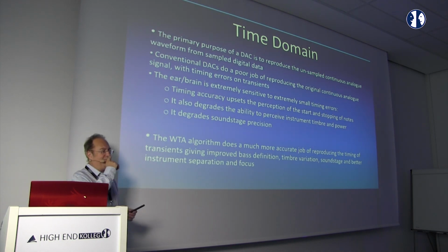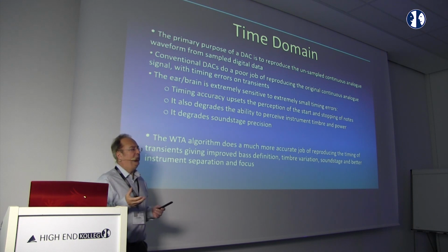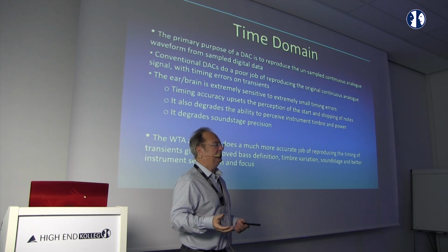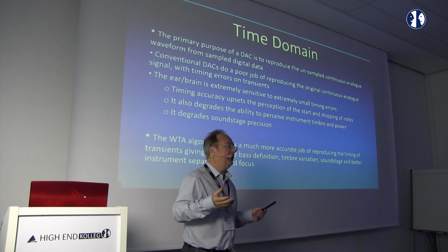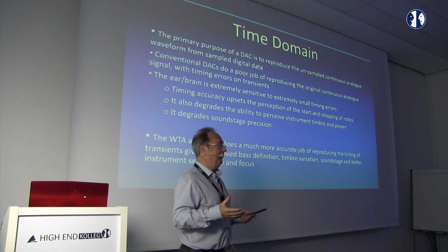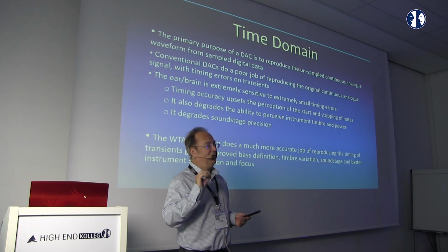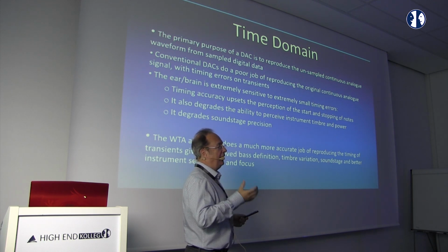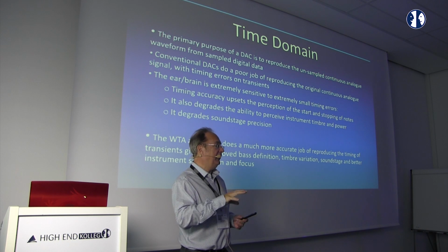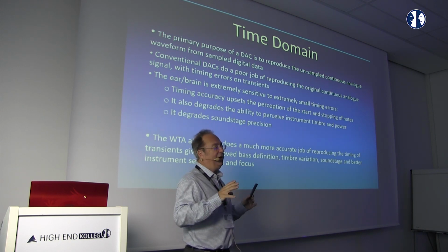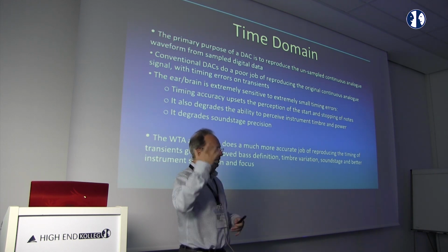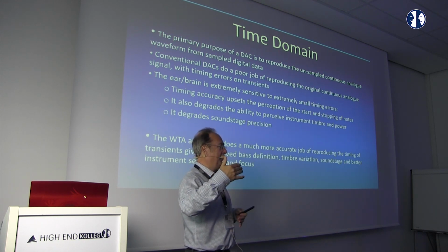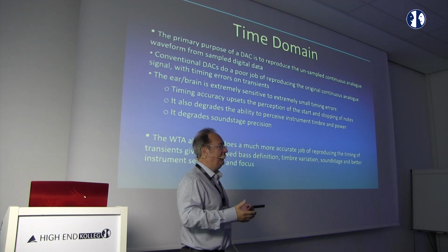So, time domain. The primary purpose of a DAC: most people think about DACs as something that reproduces digital data, and it's not an unreasonable assumption. The thing is, a DAC is not there to reproduce digital data. The DAC is there to reproduce the original unsampled analog signal that was in the A to D converter. And this is fundamentally a very different approach to most DAC designers, because they think entirely about reproducing digital data, hence the popularity of NOS DACs, when all they do is keep the original digital data.